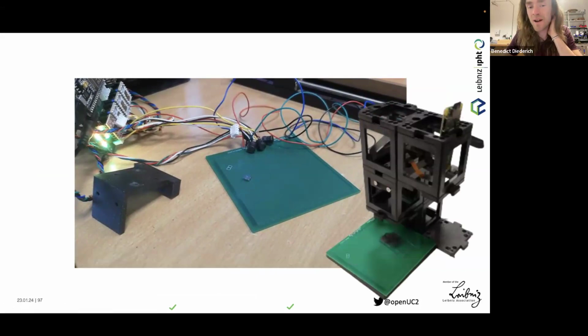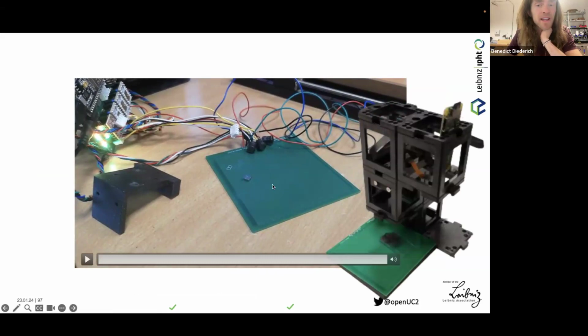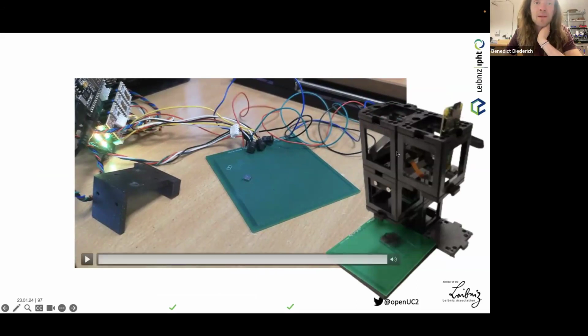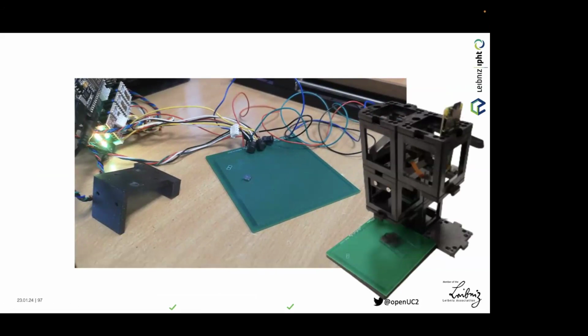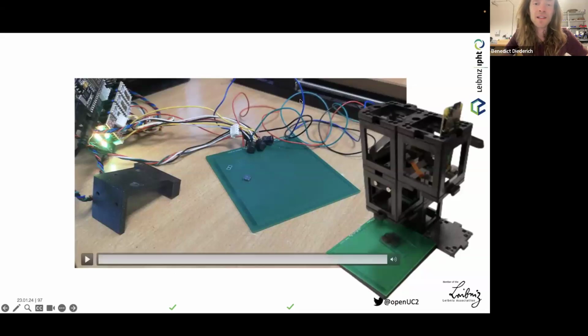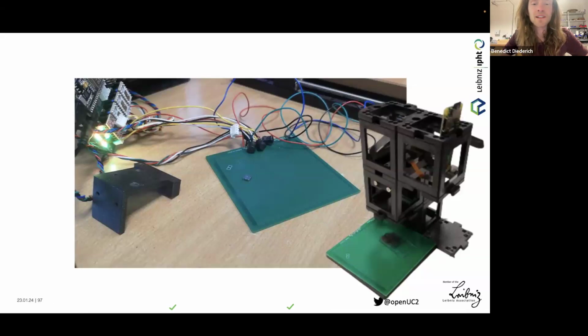The hope is, together with optical feedback, to have a controlled XY scanning in a microscope that's essentially created by these little cubes with UC2 and a little Raspberry Pi camera, and take away all the load of building an XY stage and also paying for it, because usually it's very expensive, with a kind of solid state device, which costs almost nothing. This is very nice, because you can use a lot of the tools from the maker communities.